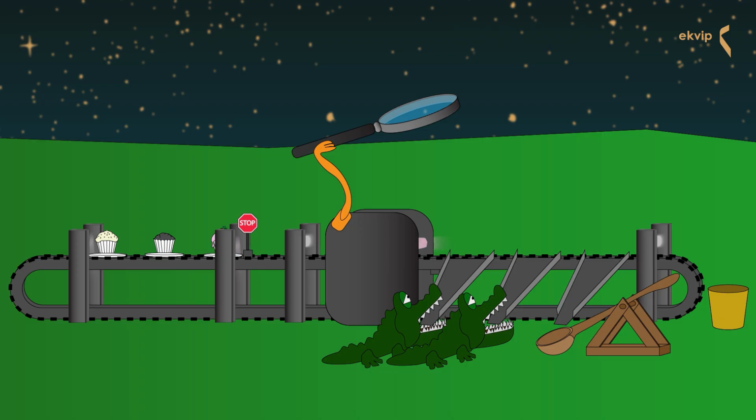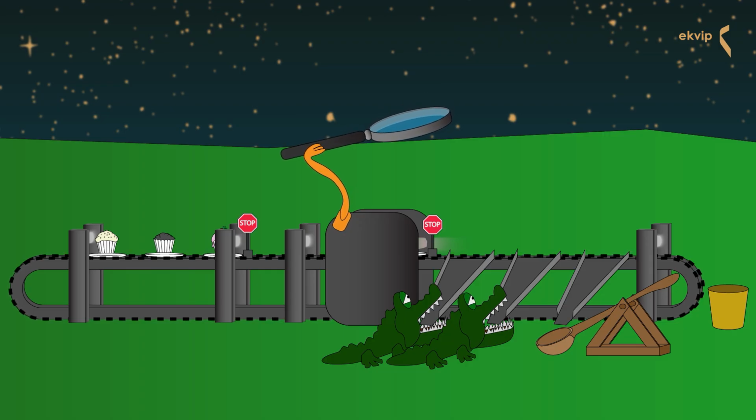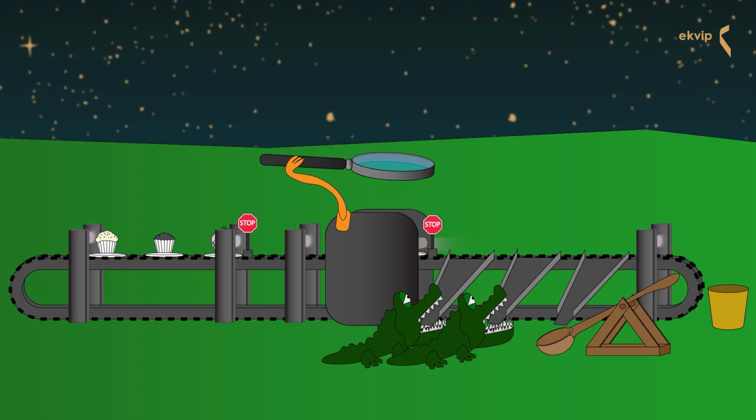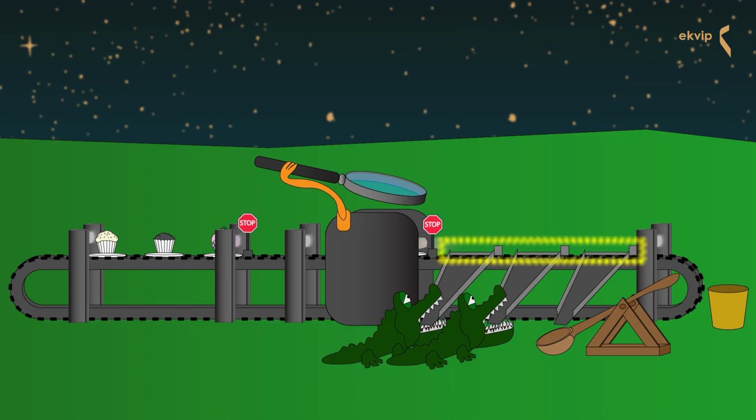After a cupcake has passed all 3 light barriers, it reaches an image recognition station. Here, it passes another light barrier that activates a stopper for the vision system. The station identifies the type of cupcake by taking an image of the cupcake and sends image data and size to the PLC. Based on this information, one of 3 lift transfer units in the next section of the line is activated.